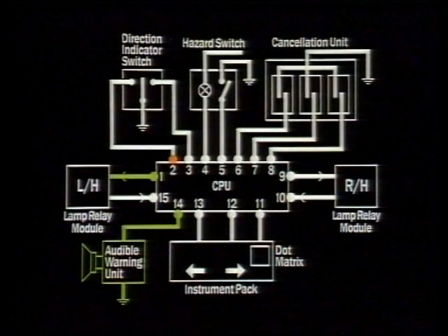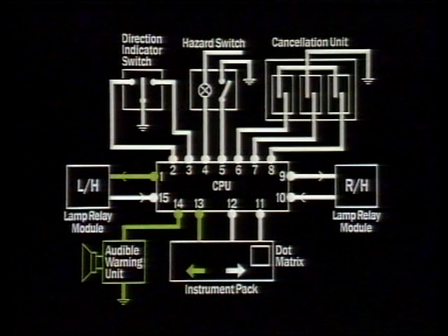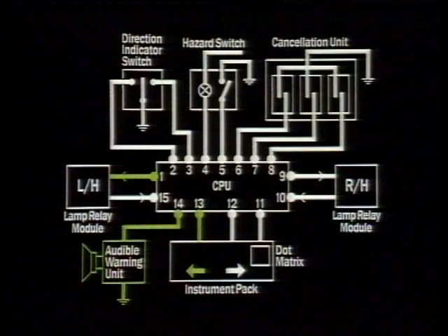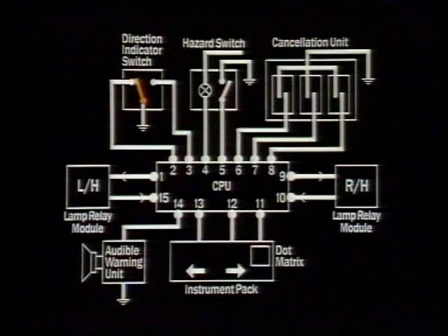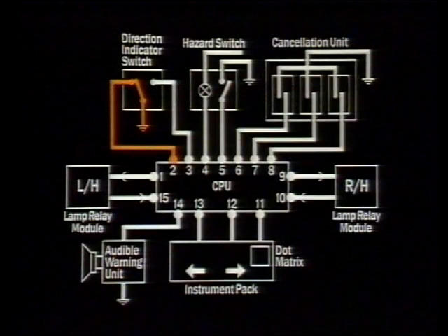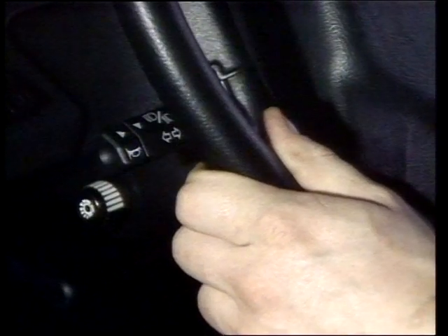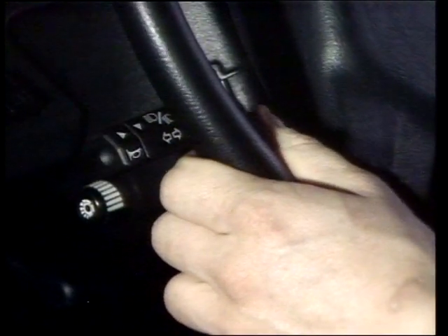Yes, the third signal that the CPU will output is at pin 13, operating the left arrow on the instrument pack in time with the sound emitted from the audible warning unit and its speaker. Let's just go through that again. The driver pushes the indicator switch down. He wants to turn left. The momentary action switch returns to its central position.